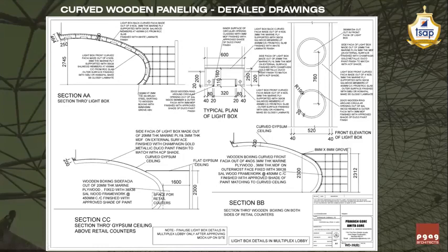If I have not written the specification so much in detail, then the contractor will not use the framing at 450 mm center to center. He might use this at maybe 700 mm center to center, and then the strength of the paneling will get compromised. Secondly, if I do not write 4 numbers of 3 mm thick marine plywood, he will not give the thickness of the paneling as desired for the sturdiness of the paneling.